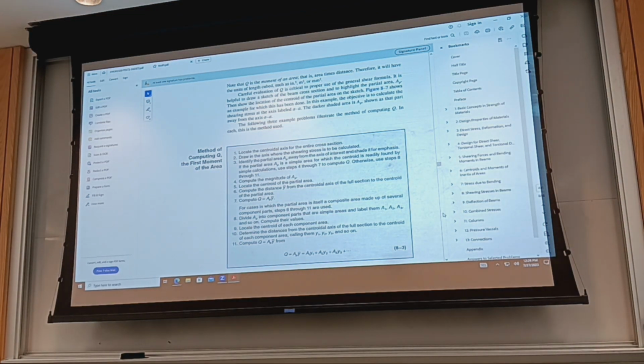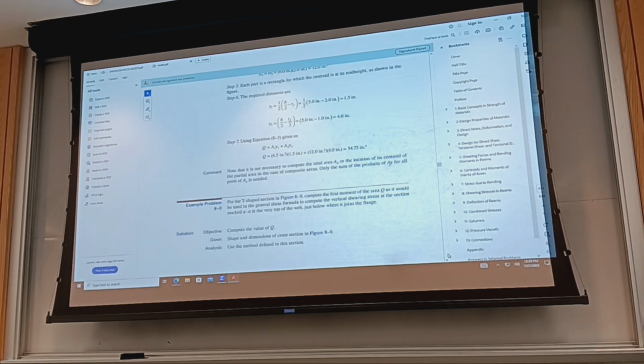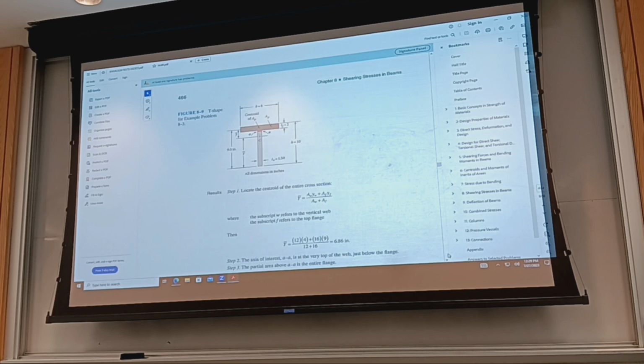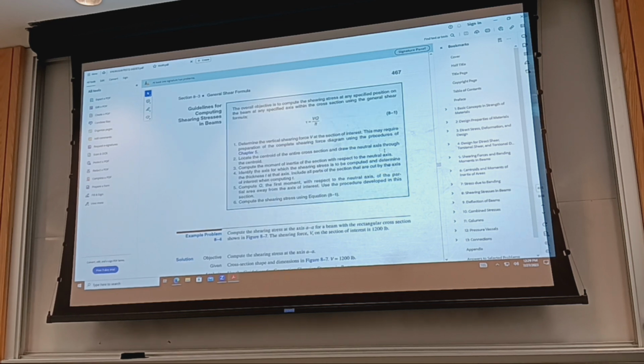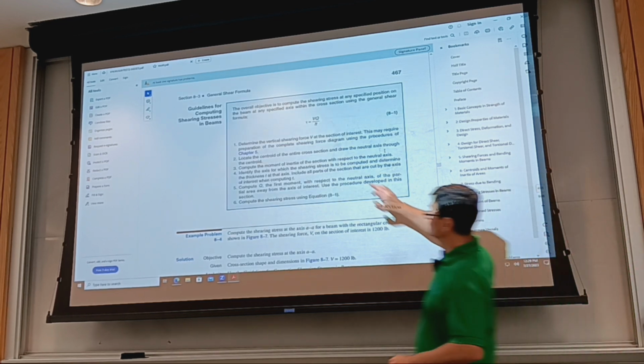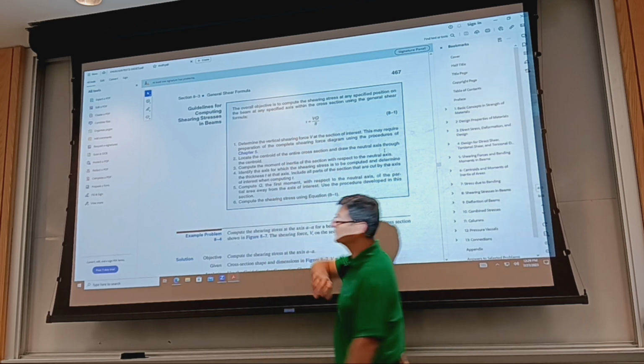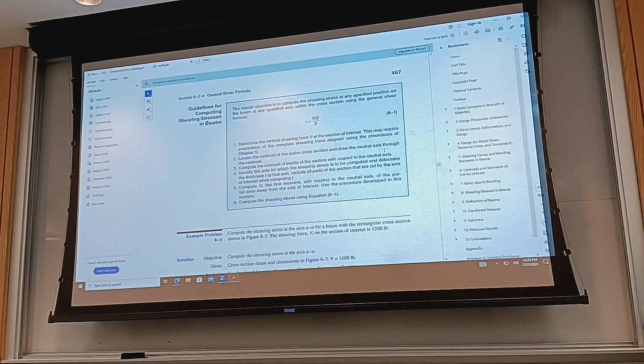Areas themselves are really easy to evaluate. Okay. So, in order to evaluate that shear stress caused by shearing force, you need first to draw the load diagram, that is reaction to supports given the external loads, and draw the shear diagram, and then take care of the first moment of area, figure out area moment of inertia, and then thickness at the location, and that's it.